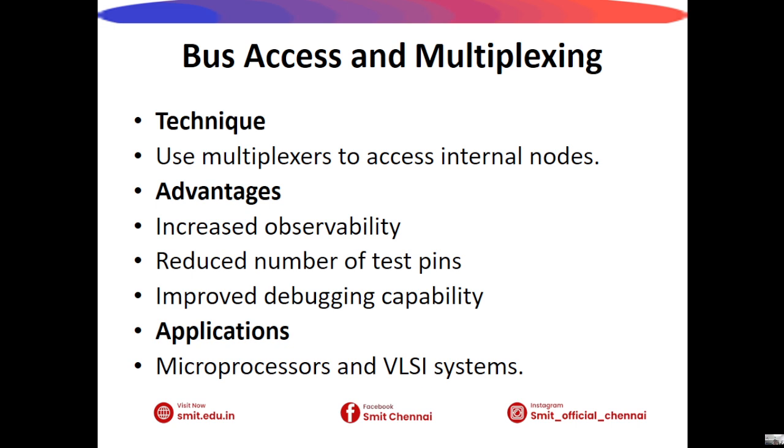Next, we see about bus access and multiplexing. Multiplexers can be used to route internal signals to output pins during testing. This technique increases observability without requiring a large number of additional output pins. It is widely used in microprocessors and complex VLSI circuits.